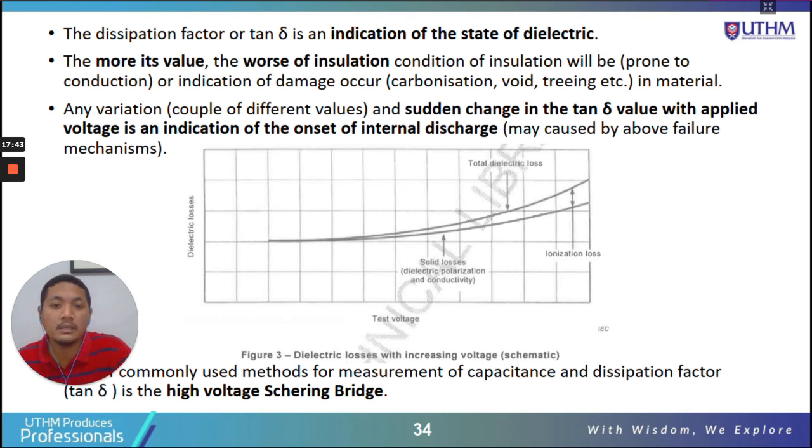You can see here, this is the tan delta value, the dielectric loss value. If we increase the supply voltage of the tan delta test, where we have to inject an AC supply, the tan delta value will also increase.